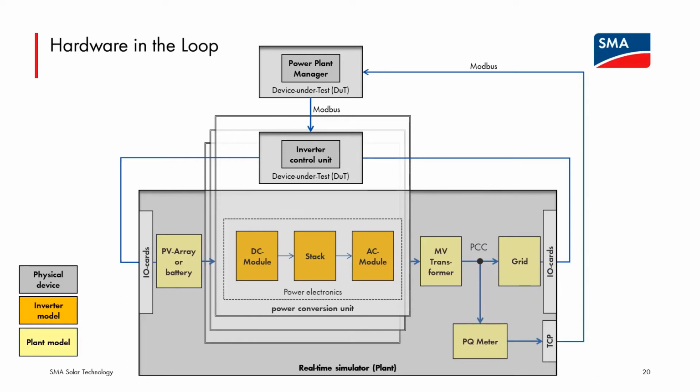But sometimes people are just interested in the control behavior of our equipment rather than having the physical device available at hand. A typical application case, for instance, is a customer designing a microgrid, maybe with Sunny Central storage battery inverters, maybe in grid-forming mode, being the only voltage source forming an isolated grid. And then he wants to test the behavior of his real physical protection relays. He wants to know how to tune and parameterize his protection settings to handle fault conditions.